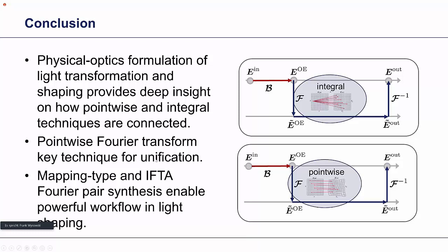And if you do integral Fourier transforms and pointwise Fourier transforms in your algorithm, as we do also in our software, that requires quite sophisticated sampling techniques. So we typically have hybrid sampling. We use equidistant Nyquist sampling for part of the field, and spline interpolation and Zernike fitting techniques for other parts of the field. So we have a hybrid sampling concept.